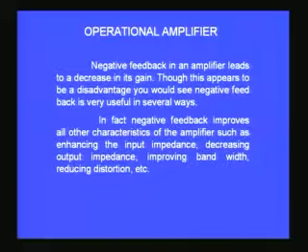You can intuitively guess that when you give negative feedback, the gain will decrease, and it is indeed true that when you give negative feedback in an amplifier, the gain will decrease. So though you feel that this will be a disadvantage to the amplifier, because you do not want the gain to decrease, you want the gain to be more, you can see this is a great advantage in several other parameters of an amplifier, like input impedance, output impedance, bandwidth, distortion.